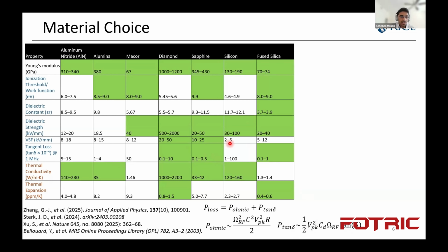And you can see it here. And the thermal conductivity, yes, well, now you're dumping a lot of RF power into this small footprint of an ion trap, and it would be great if all that heat redistributes within itself and can be distributed very nicely to a heatsink. So for that reason, it's better to have something similar to diamond or sapphire, and fused silica is deficient in it. But by having very good thermal interfacing materials like the aluminum nitride we use, we can mitigate it.